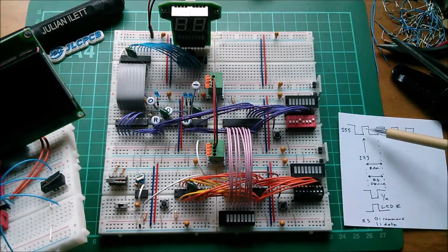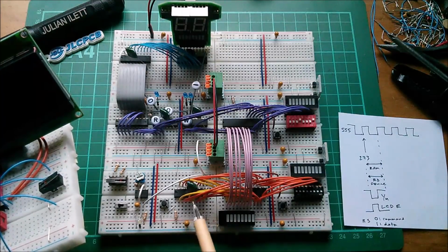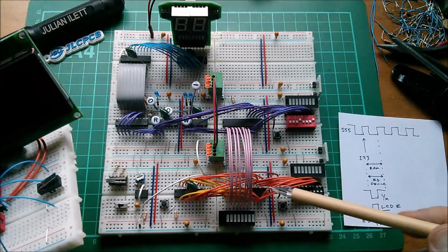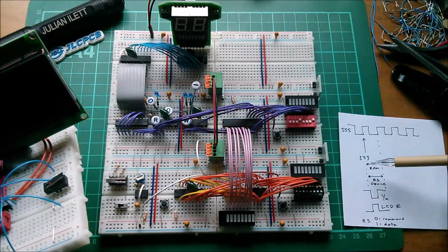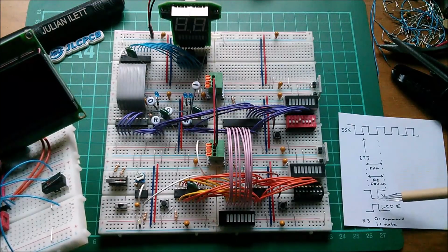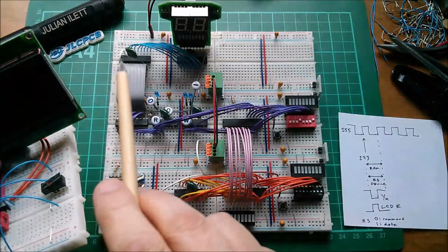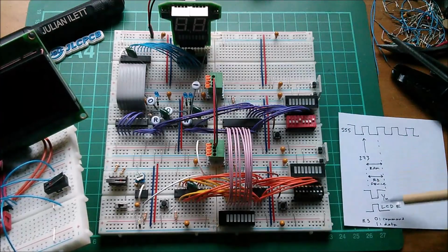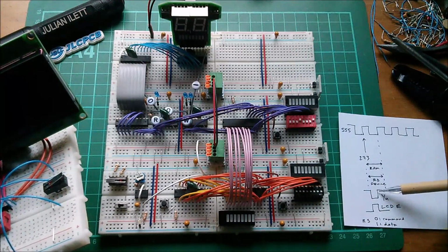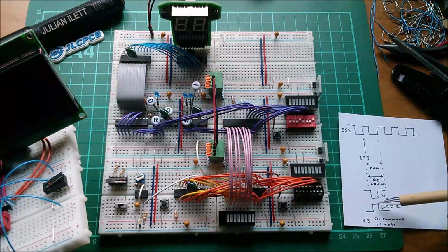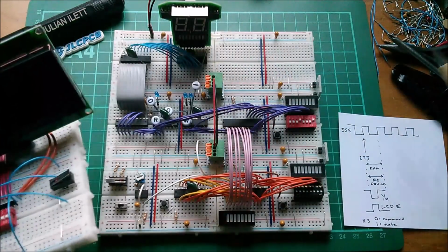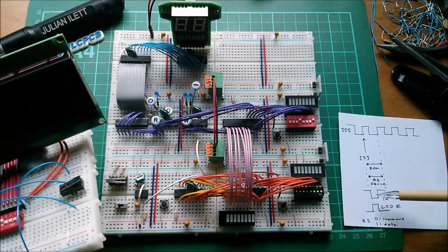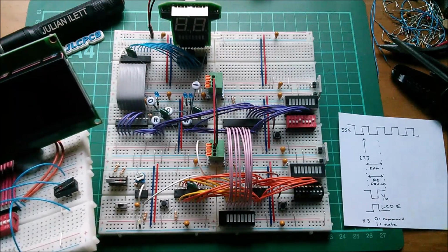So here's my 555 clock. The rising edge of that triggers the 273, this one, which latches new RAM data onto the 2 parts of the computer. So it's stable during this period, which means that to latch from a readable device to a writable device, it has to happen halfway through that period, and that's that rising edge. But the LCD requires, and I believe it's the falling edge that actually latches the data bus data into the display. So I'm going to use a transistor to invert that signal.